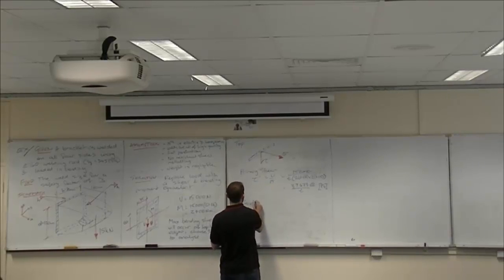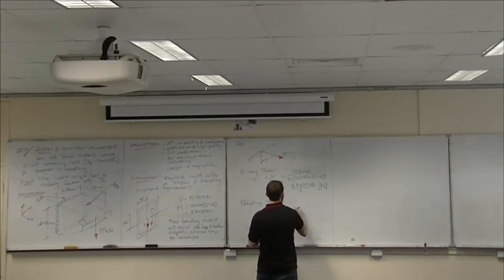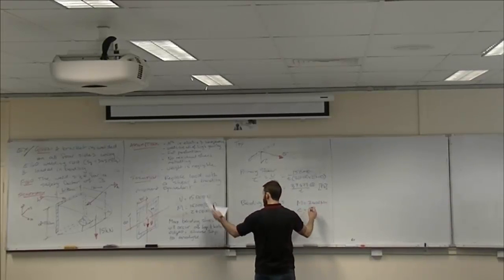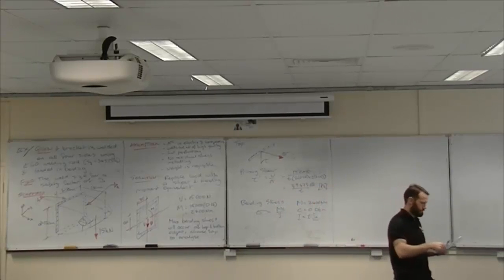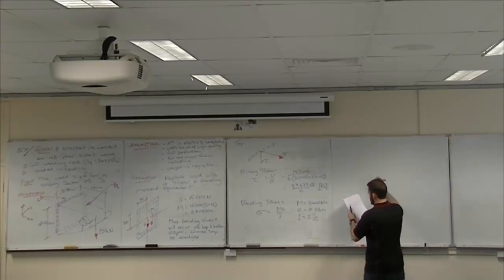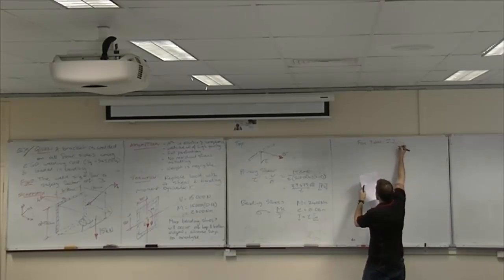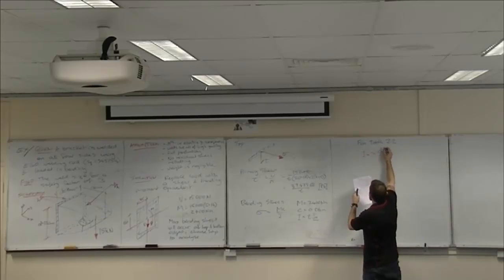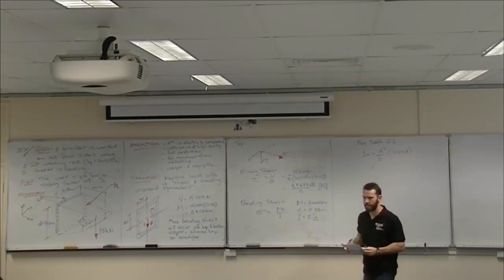Alright, bending stress. Sigma equals Mc on I. And our values, M equals 2400 newton meters, c equals half the height, which is 0.06 meters, I equals t times Iu, and we need to calculate Iu from our sheet. d squared on 6, 3b plus d. Alright. Everyone calculate that, tell me.